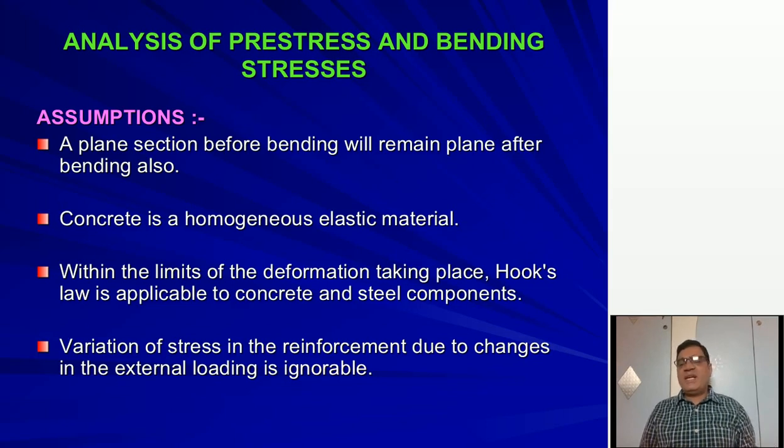Now, the design is based on the following assumptions. The first one is plane section before bending will remain plane after bending also. Concrete is a homogeneous elastic material. Third, within the limits of deformation taking place, Hooke's law is applicable to concrete and steel components. And the last one, variation of stress in the reinforcement due to changes in the external loading is ignorable. Almost all these assumptions we use even for RCC structure.